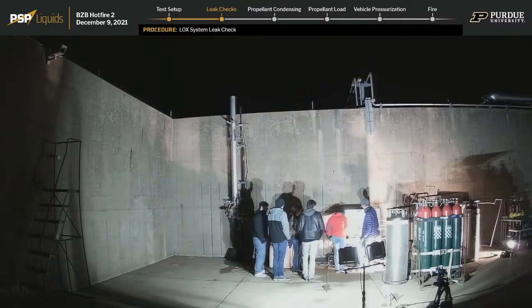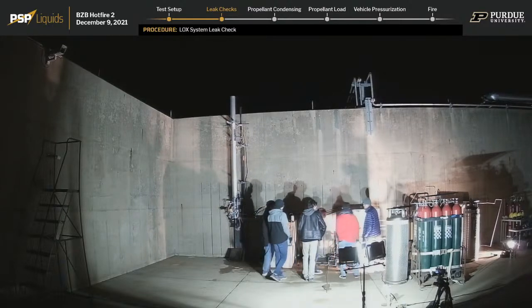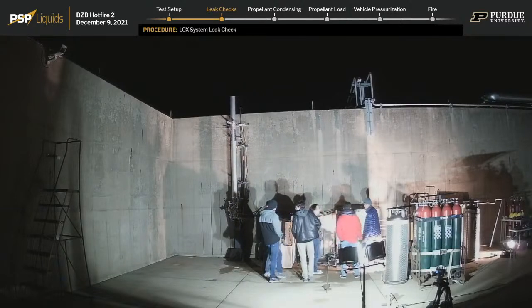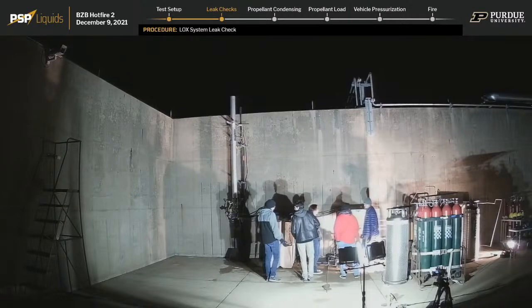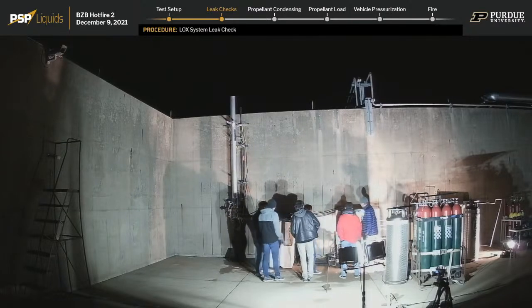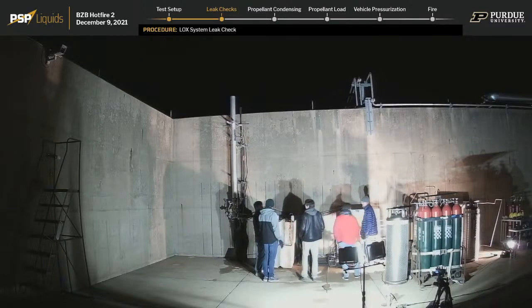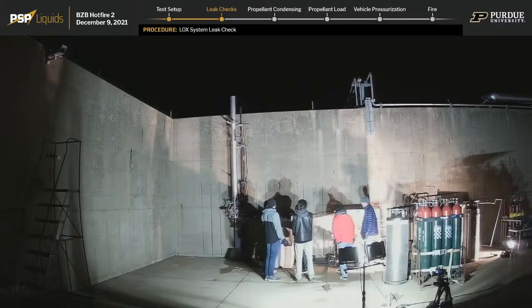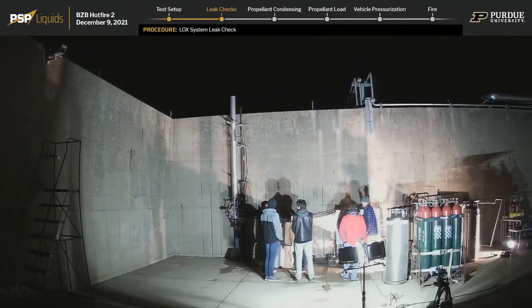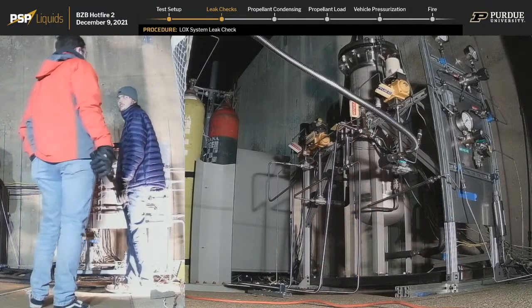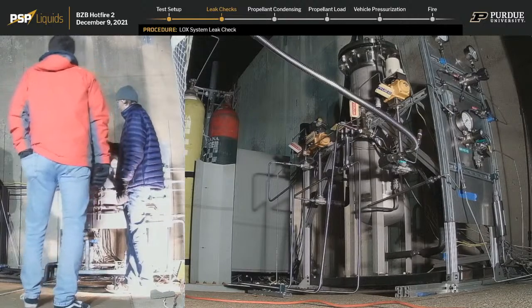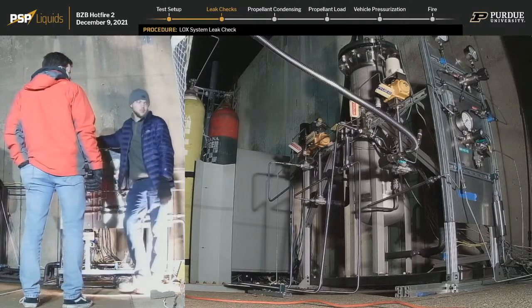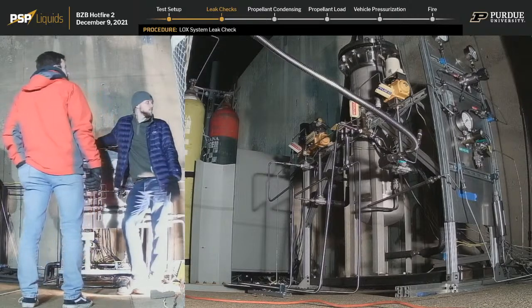So what we're doing right now is getting a leak rate for the overall system. Jack, do you want to talk about what a leak rate is for a second and why it's important to give for a system? So, in a liquid rocket such as ours, we have not only the rocket to worry about filling, but also a ground support system to support the rocket. Our ground support system, BCLS, or the Black Cat Launch System, has the ability to automatically fill our propellants into the vehicle to make sure our operators are safely behind cover. In our fluid system, we have a bunch of fitting connections for all of our plumbing, so all of our fluids can make their way into the rocket. On this fluid system, these fittings can be leak points.